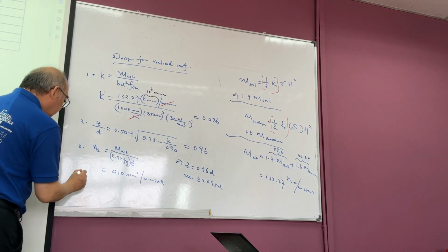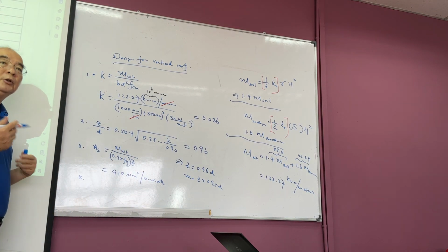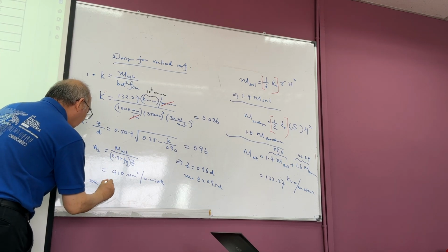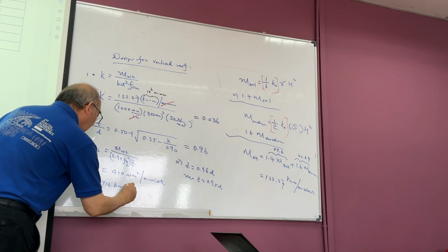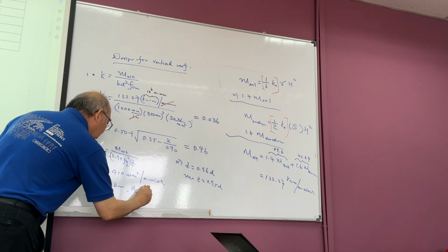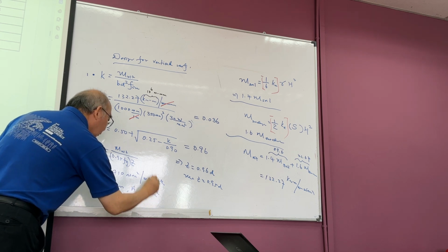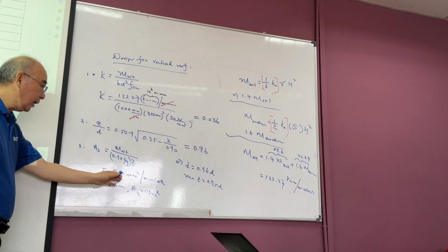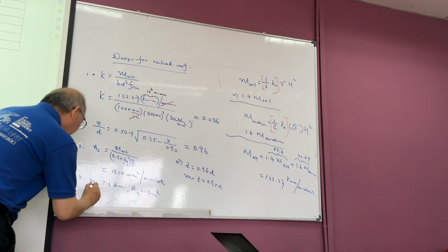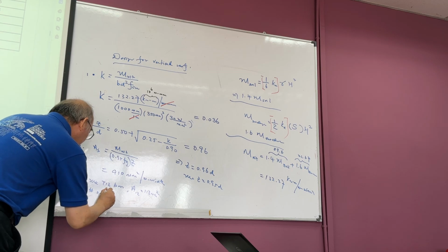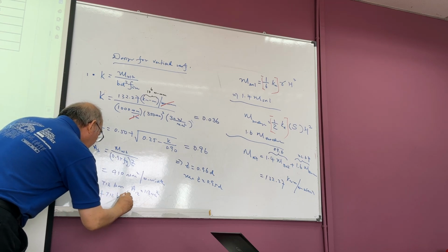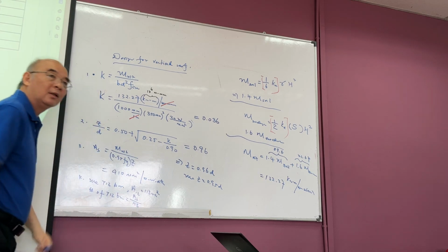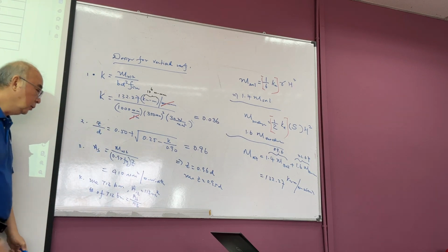Let's say I use T12 bars. Area of T12 bars is 113 millimeter square. Okay, so how many bars? It will be 910 divided by 113. So number of T12 bars equals AS divided by 113. What's that? So this is equal to how many?